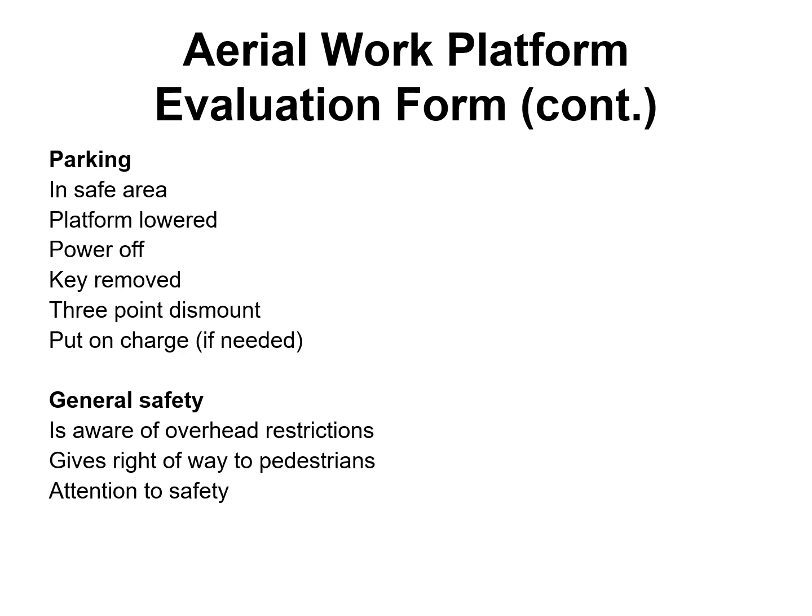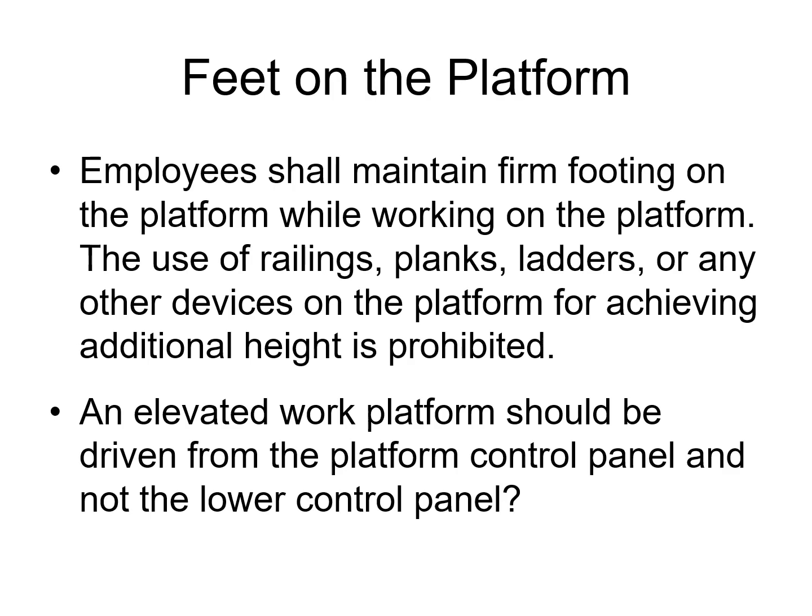When we park the platform, we want to park it in a safe area. We want to lower the platform, turn the power off, remove the key, use the 3-point dismount, and if we're charging, we want to put the charge on. General safety. Is aware of overhead restrictions, gives the right of way to pedestrians, and is attention to safety. Feet on the platform.